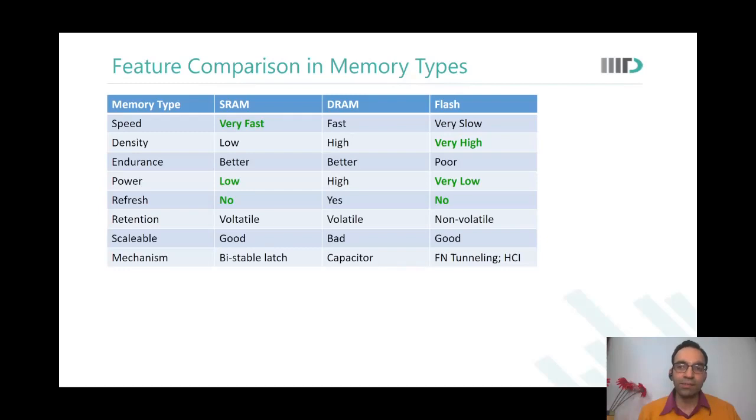Okay. Akash? Sir, you mentioned that in the phone, when we say 8 GB RAM or 16 GB RAM, we use DRAM there. But DRAM is slower than SRAM, and it also requires periodic refresh. But still, we use DRAM. Is it because SRAM consumes more area, a trade-off? Yes, DRAMs are much denser than SRAMs, and in memories, area is gold, diamond.